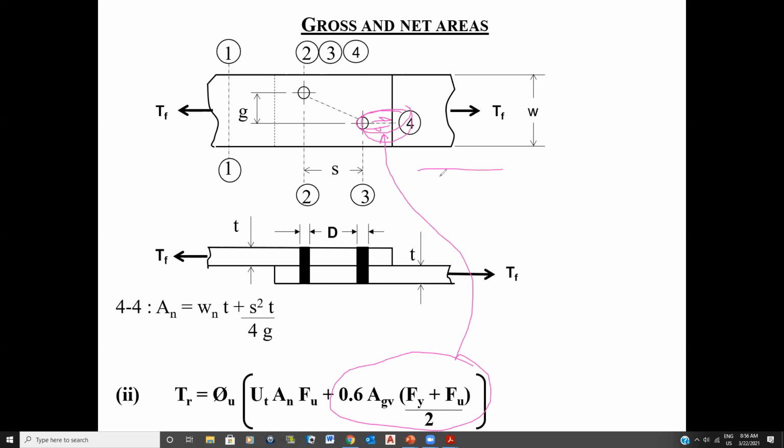When the failure is in the direction of the force, the steel is acting in shear. And therefore, the shear resistance of steel is weaker than the tensile resistance. And this is how you calculate the shear resistance of the steel. But that would be only for this little part here. So all of this here up to here would be calculated by this, then this part here would be calculated by that. And that's what this equation does. If there's any section in your failure plane that's in shear, then you have this component here that you use to evaluate that little section that's in shear.